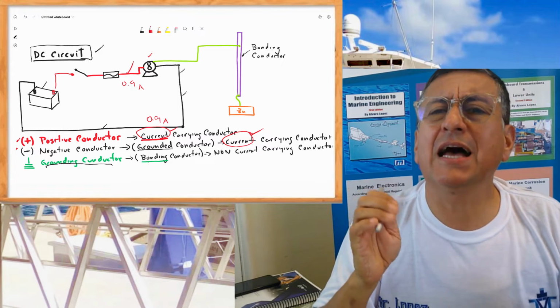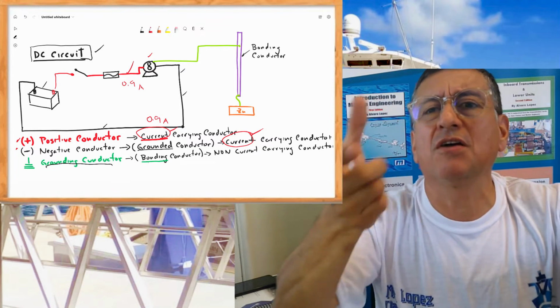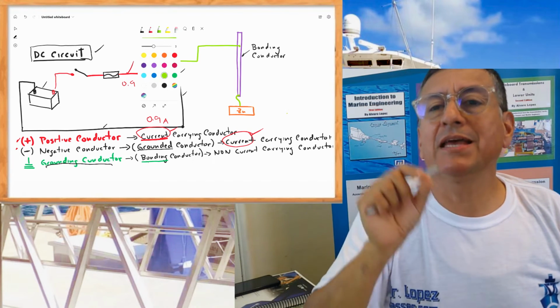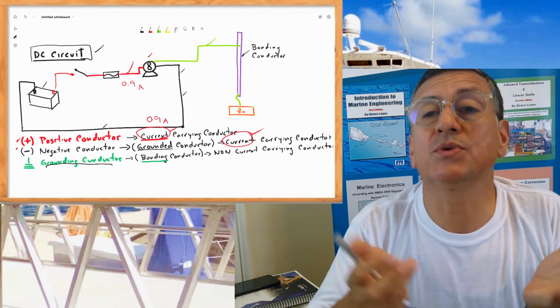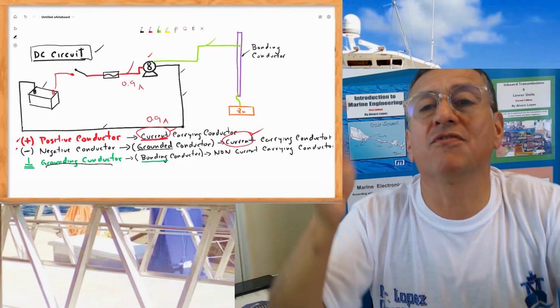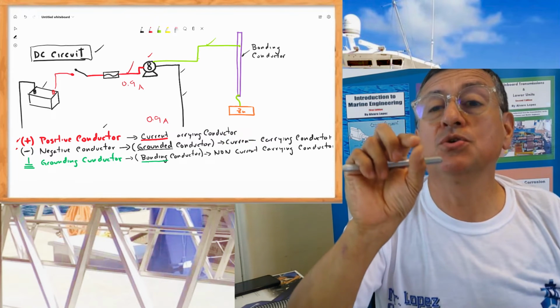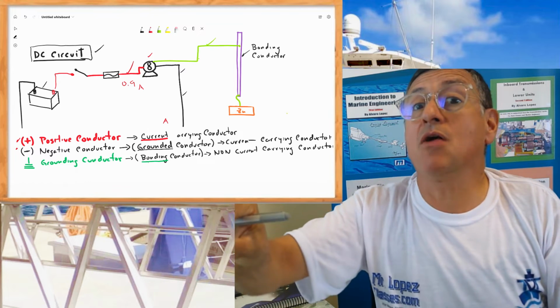What about that green cable that I have in the majority of the appliances and devices? That green cable is the cable that is used to drain static electricity accumulated in the case of the equipment. The static electricity should be drained with that green cable connected to the ground of my home.